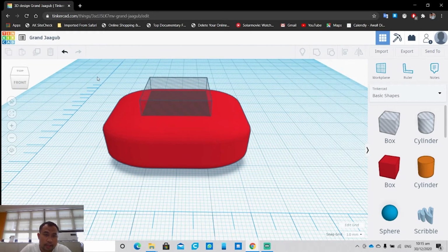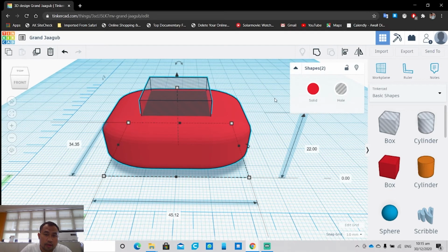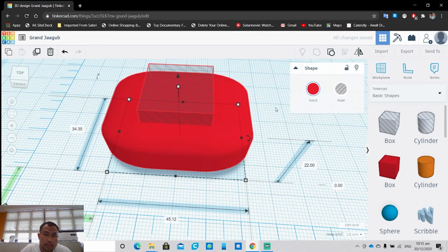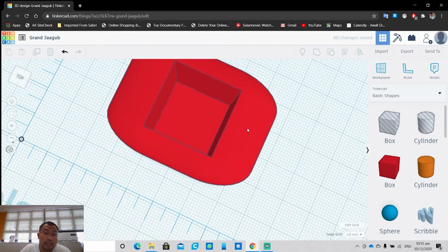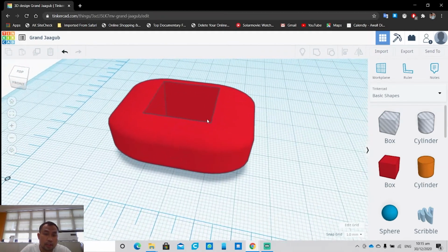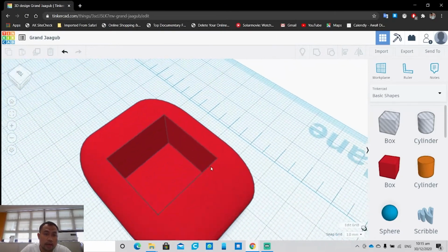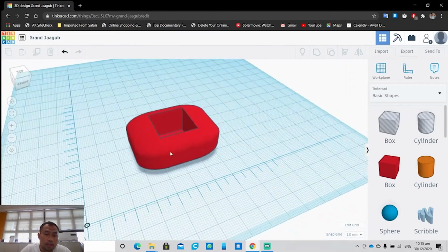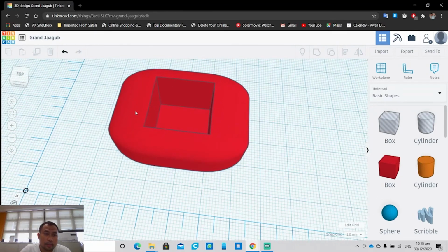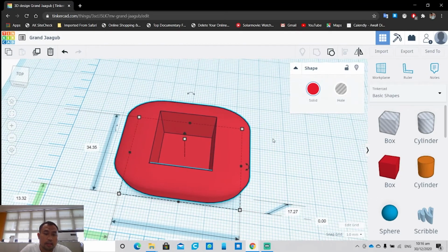So what you're gonna do next is that I am gonna control click both of these individual shapes and click on this group tool. So control G. So what happens here is that I'm gonna merge these two items and create a new object, which is a hollow shape box, as you can see, right? So I'm gonna center the view on it.